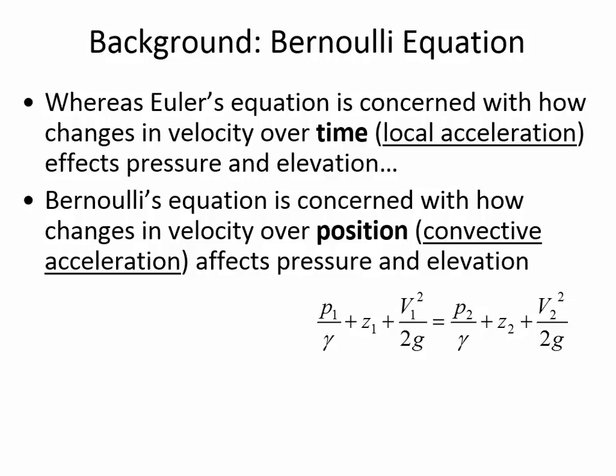So we can find out what's the velocity here, maybe through a velocity profile if conditions are laminar, or through a measurement. So it doesn't have to be the center line velocity. And oftentimes what they'll do is use the average velocity for the cross section. The easiest way to find the average velocity for a cross section is to look at the flow rate and divide it by the area through which flow is traveling. So that's a common approach, to use V bar, which means the average velocity. But if we have more specific information, we can use that too for a certain spot.